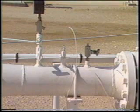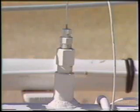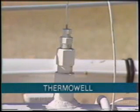The thermal well provides a location where the temperature of the natural gas can be measured. Since thermal wells can create unwanted turbulence, they are usually located downstream of the orifice plate.